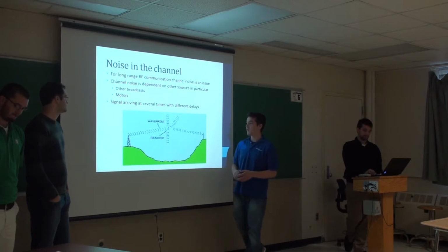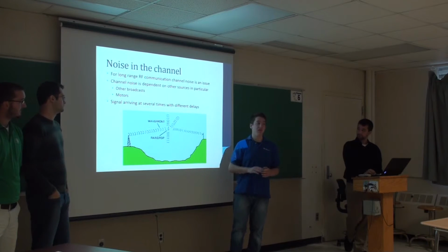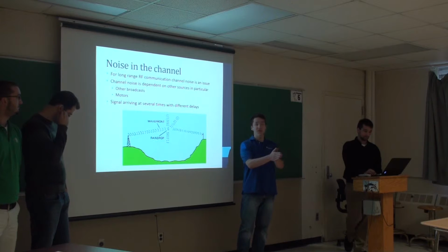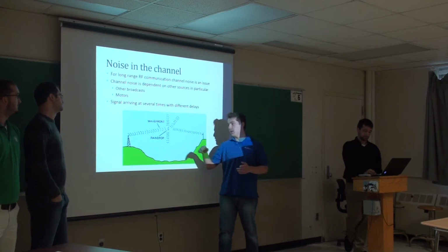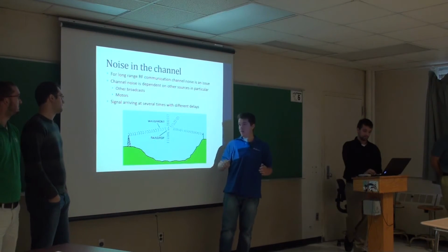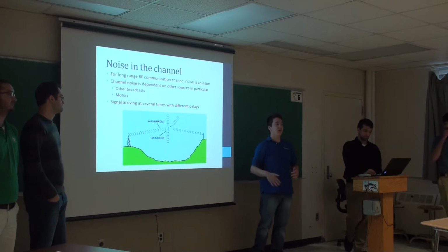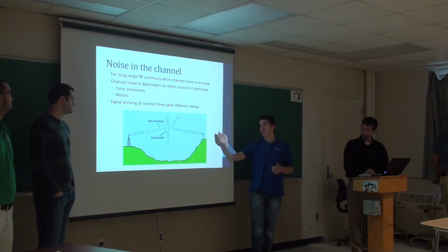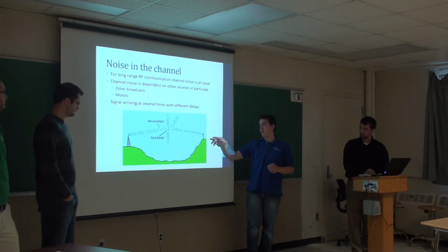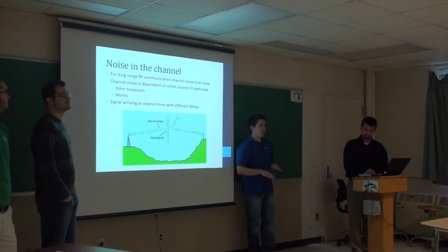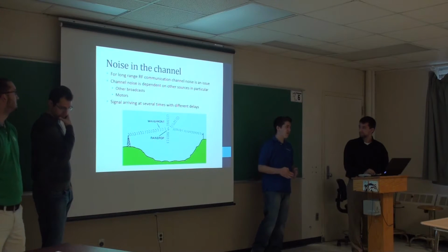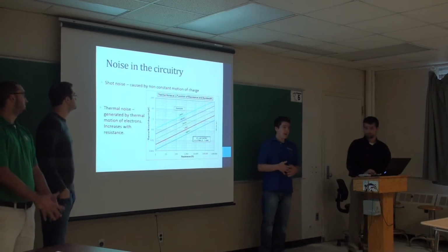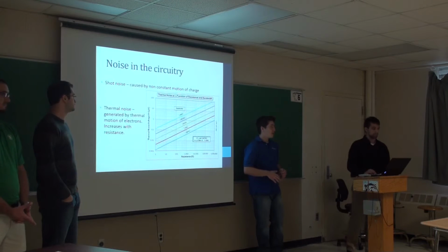So for instance, if you're transmitting from one tower to another, obviously your signal is going to take the direct path, but because we don't have 100% amazing directive antennas, it's also going to scatter in all other directions, and some of that signal might go into the upper atmosphere and reflect off a rain cloud, and it's going to also come down, and there's going to be a slight time delay between the arrival of the signal on the direct path and then a delayed version of the signal. So you have this time dispersion, which is also another factor that you have to consider when you're doing modulation and demodulation.